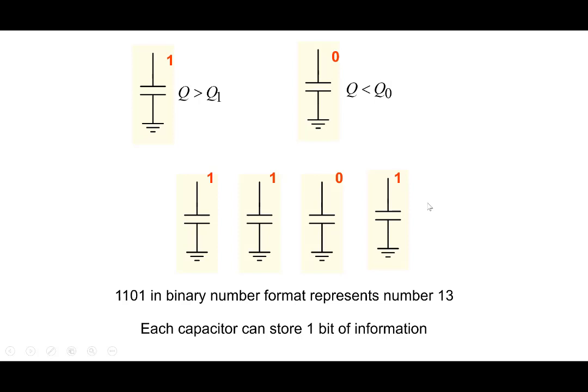So how do we store data into a DRAM, and how do we read data from a DRAM? We do that by using a transistor. The MOSFET that we just studied, we use that as a switch to charge and discharge a capacitor. For example, I want to charge up this capacitor, store a 1. So what I will do is apply a voltage to the gate here, and the gate will turn my MOSFET on, and the MOSFET acts like a sort of low resistance switch here, and 2.5 volts will go and charge up this capacitor.